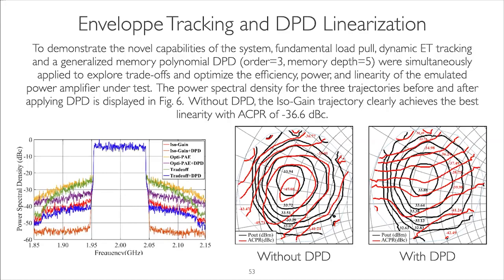You can see here on the right, there are different ACPR measurements, where the optimum on the left is minus 48 dBc versus on the right roughly minus 40, minus 41. So definitely an improvement if you had not used the DPD algorithm.